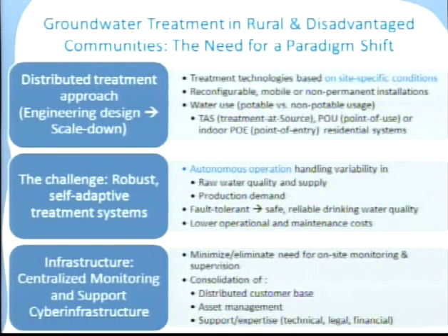We can implement model-based control by understanding how the ion exchange system works and actually predict in advance what might happen using various sensors that tell us, have we reached that breakthrough point in the ion exchange resin?